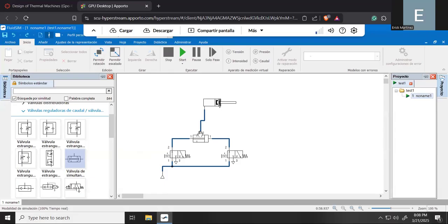Okay, so this only works when you apply pressure in the 2 points of these two pressure valves in order to allow the pressure or the air pressure to flow from port number 2 to the chamber of the single acting cylinder. Okay, so this is the way it works.